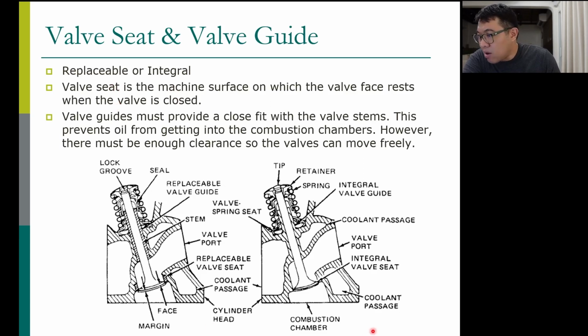Now this valve seat is a machined surface that the valve face rests on when it closes. So basically it has to seal the combustion chamber. The valve guide provides a close fit for the valve stem, such that we can control it, but not too tight, otherwise the valve cannot move, right?